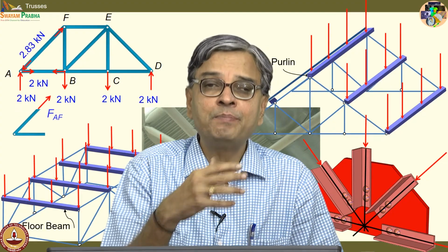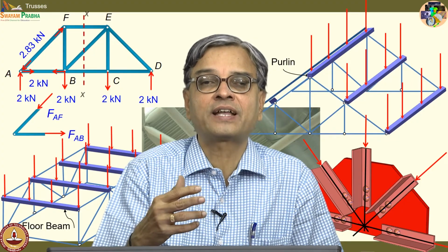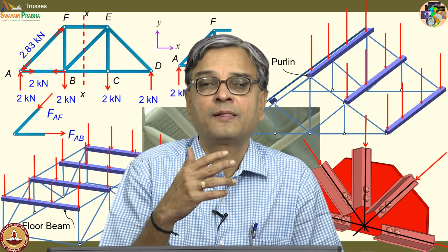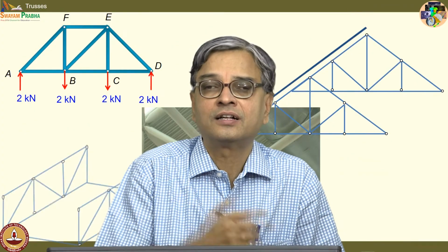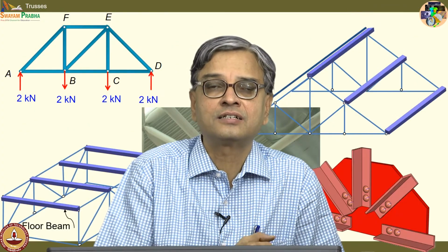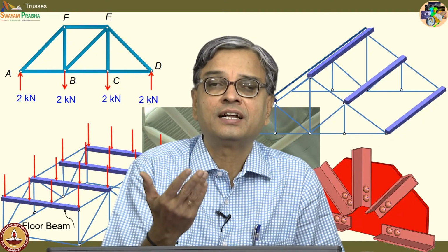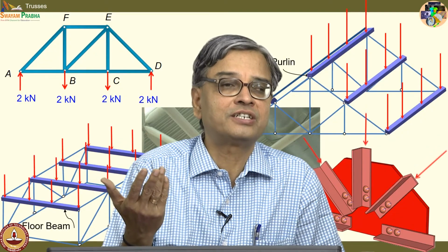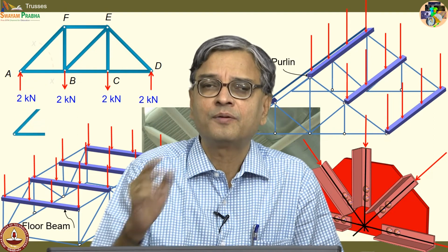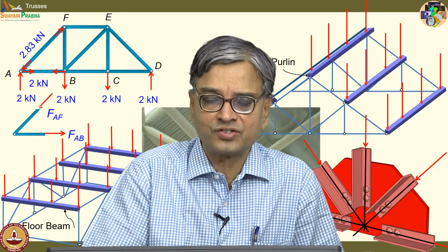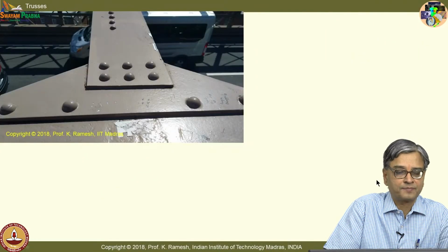So, there is an inbuilt crack arrest mechanism available in riveted construction, and when you go home for your mid semester recess, you would see in many railway bridges they are all riveted connections. Keep your eyes open, keep your head out and see what those are.